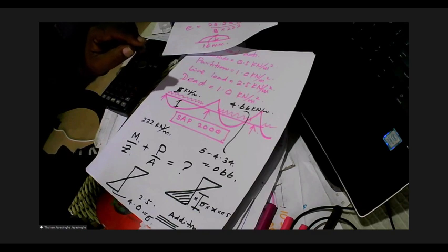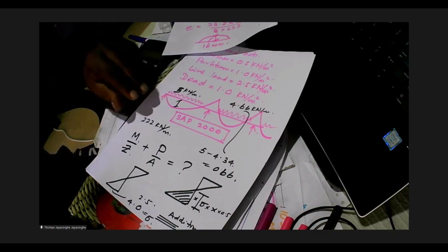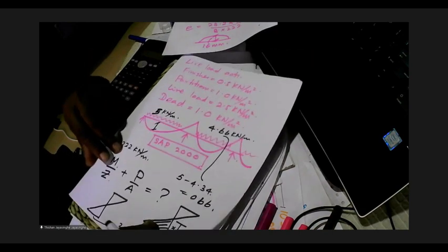So we can have a band of about 1 meter width to have a concentration of cables. So in the band, now you have to design the band. We got 8 meter spans in that direction, so you get 8 meter spans, 200 millimeter slab.